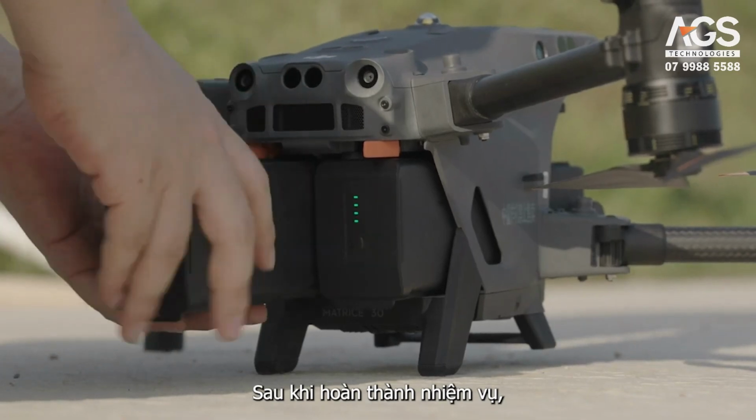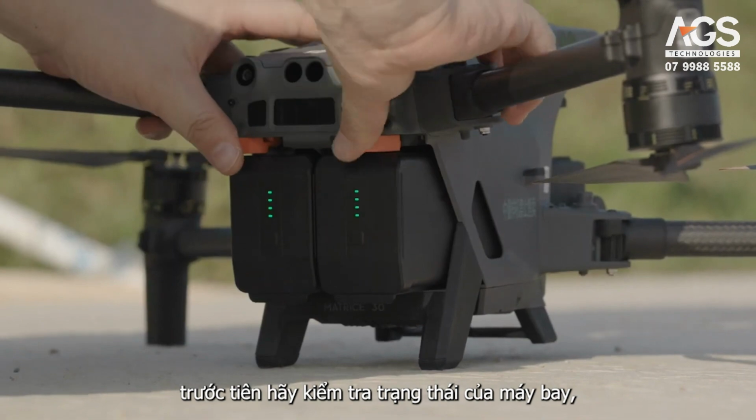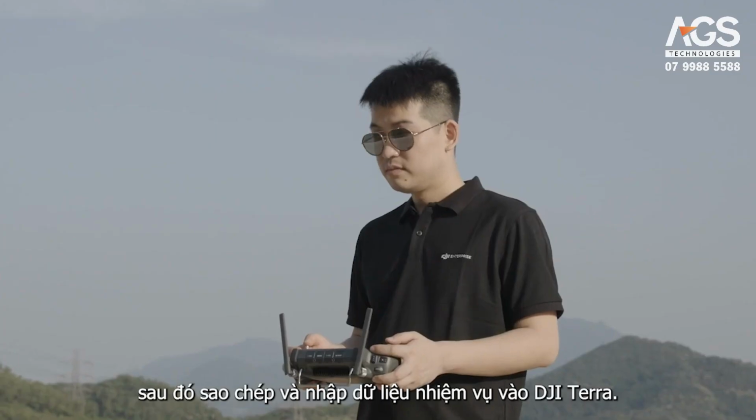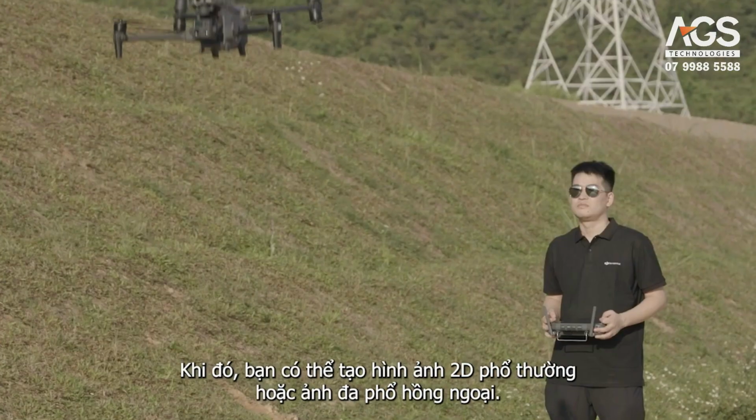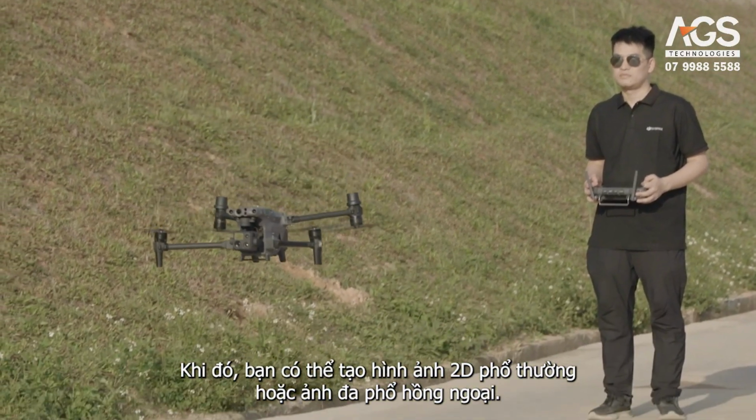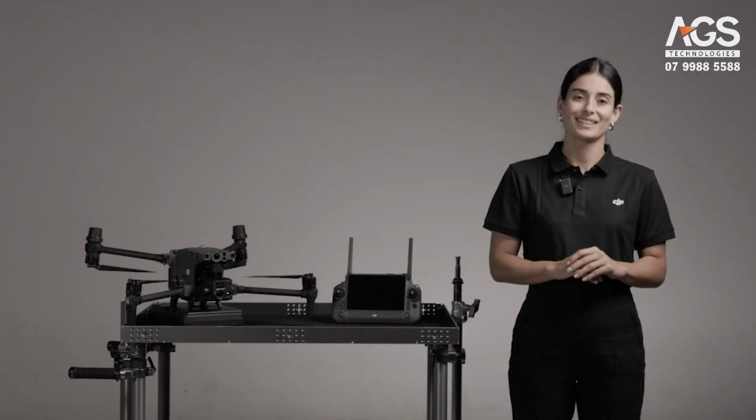After completing the mission, check the status of the aircraft first. Then, transfer the mission data from the aircraft to DJI Terra, and you can generate 2D visible light or infrared orthophotos. Thanks for watching!